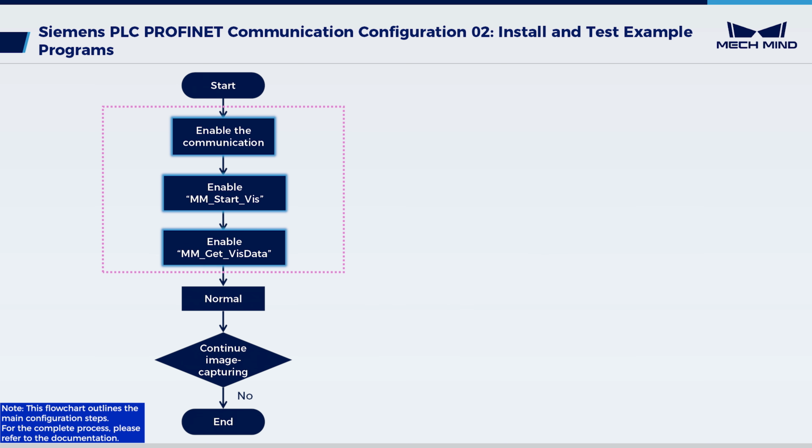Next, let's move on to the actual configuration. Before testing, make sure the Vision project status is set to Auto-Load Solution. Then, enable communication in TIA Portal. In Camera I/O, expand the group To Camera. Double-click the monitor value of COM Enable.